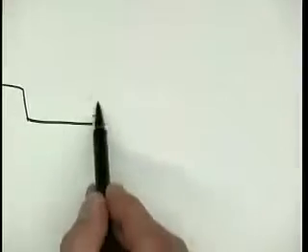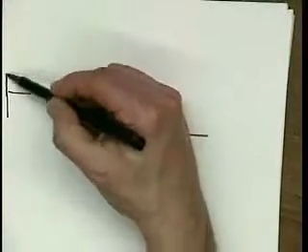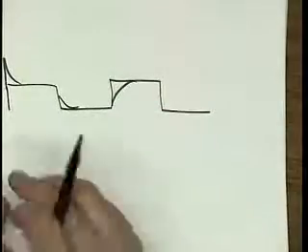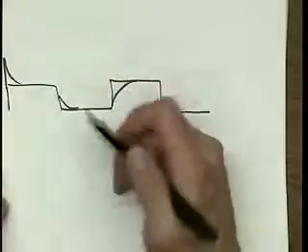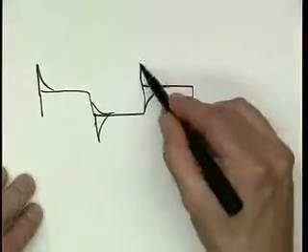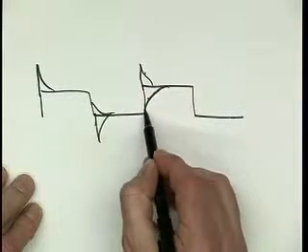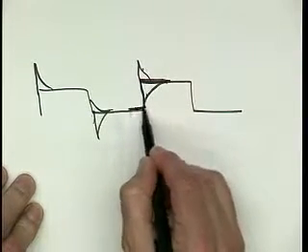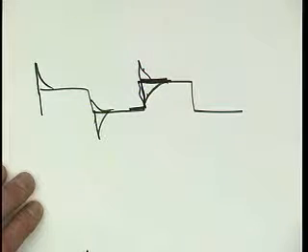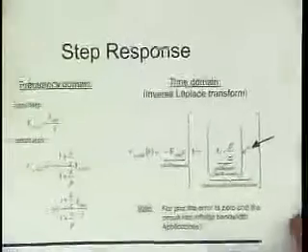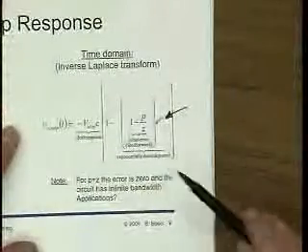Yeah, the ideal square wave is going to look like this. But when you first turn it in, it's going to look like this, or maybe it's going to look like this. As you turn the screw, you can get from this situation to that situation. In the middle somewhere, you get this situation. That's when P equals C. Bingo. That's what you do in an oscilloscope. Everything has a use in analog circuits, so that 0 is not such a bad thing.